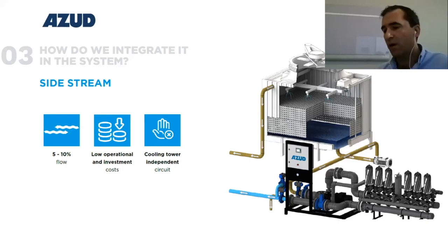The control of biological growth can mitigate potential health problems also, such as those caused by Legionella. The use of side stream filtration can minimize habitat surfaces and nutrients by maintaining lower particle levels in the water stream.